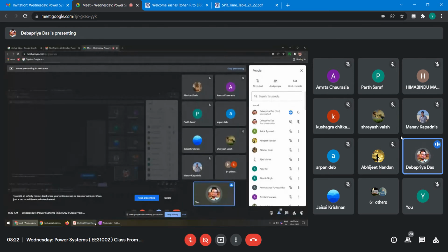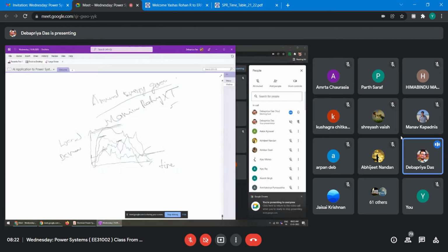That means as a whole, if you take that, for example, just hold on. Let me go to this. For example, I draw many things, right? So this is an individual maximum demand. This is another individual maximum demand. This is another individual maximum demand. But when you come here at the peak, no peak is happening here, right? So whatever its peak, it may be less than that. Some fraction is there, C1. Here also some fraction will be there, C2. Here also some fraction will be there, C3, right? So it is not matching with this.